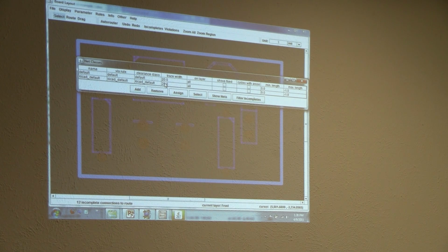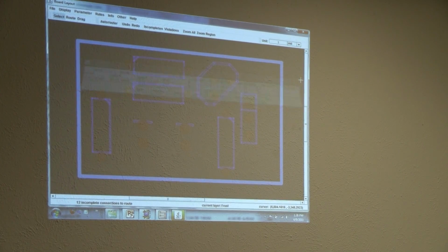Well, you can change them in here, okay, but it's harder to do than it is in KiCAD. Would you lose it then? This is web-based, so if you come back and reroute, and that's one of the things I'm going to tell you, a lot of times you don't accept the first solution from the auto router, so you'd have to come back and put them back in, and it's just not something you want to do.